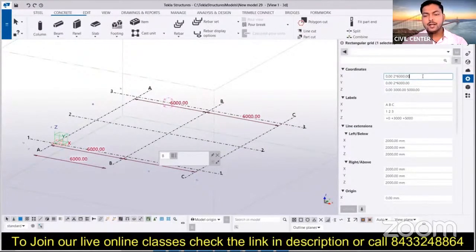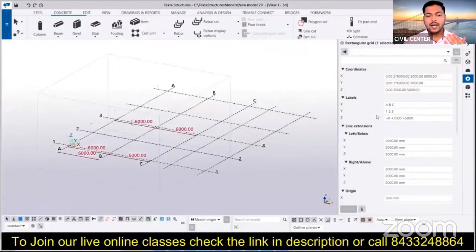So over here, if we just enter anything else, over here it is 2 into 6,000, and you have added 3,000 and 5,000, then you will create a grid line over there also. Then you can also label them according to the names. So just click on modify, and you can see you have the grid lines over here.